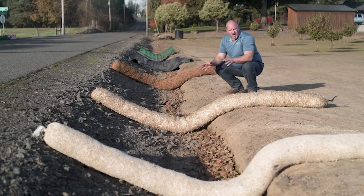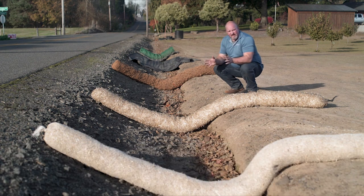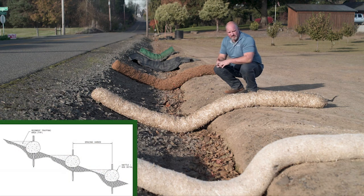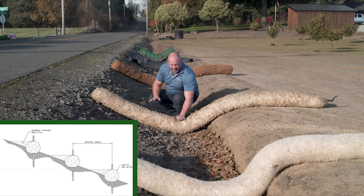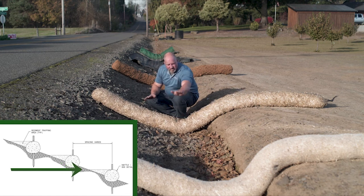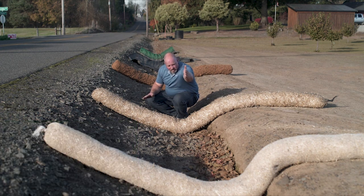The thing that's important about installing wattles is the frequency of the check dams within the slope. The steeper the slope, oftentimes the closer the wattles need to be. Without specification based on the steepness of slope, you can judge how close your wattles need to be together by looking at the downstream wattle, and as water cascades over the top of this, you want the top of this wattle to back the water up to the bottom of that wattle. So you want water coming over the top of the wattle, cascading into the water,